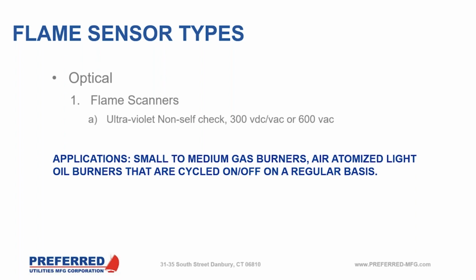So when we have zero flame signal or no UV there, we're going to have a full voltage, okay? And when we start conducting between those two, it's called pulses. The stronger the UV is, the more pulses between the two plates inside that tube. And that basically starts loading that circuit. The Flame Safeguard sees these pulses and determines the flame signal strength on the number of pulses that it's actually receiving. The more pulses, the stronger the UV signal. So we're able to determine very reliably that we have flame signal there.